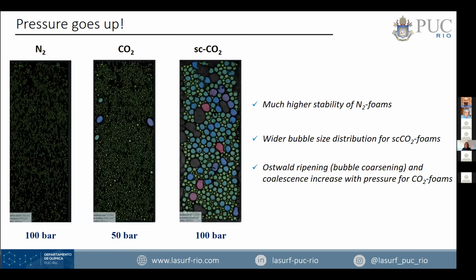And when we add nanoparticles, then as mentioned before, we get this electrostatic and steric repulsion that we expect to decrease the CO2 diffusion and increase the film resistance, in this case of the lamellas. You can see here that when we do the same kind of experiment, looking at foam stability, with nanoparticles the formulation is able to increase the foam half-life by 4 times, going from less than 1,000 seconds to about 1 hour. So even a very small amount of nanoparticles is able to arrest the coarsening of the CO2 foam.